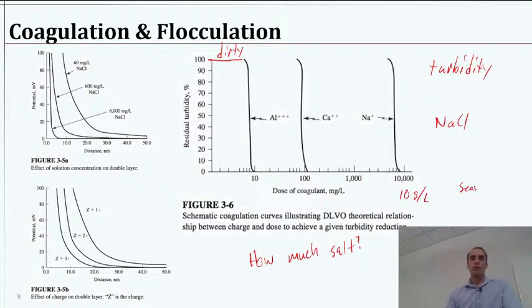Seawater is about 25 to 30 range grams per liter of salt. Lake Pontchartrain in some parts is maybe 5 grams per liter, just as a reference. So sodium, not a great idea to add that in order to cause particles to stick together. But if we look at calcium, just with a 2+, now we're looking at 100 milligrams per liter. It's quite a bit lower, 100 times smaller concentration. And that's at a point where, okay, maybe that could be relevant.